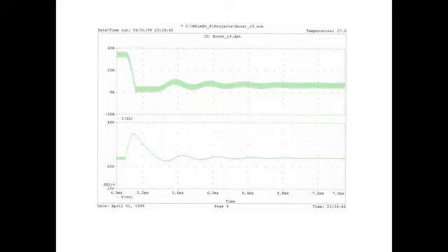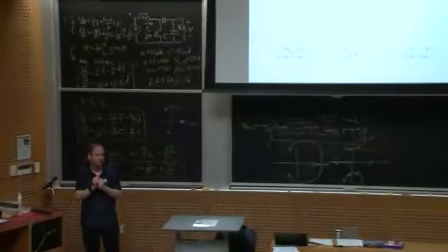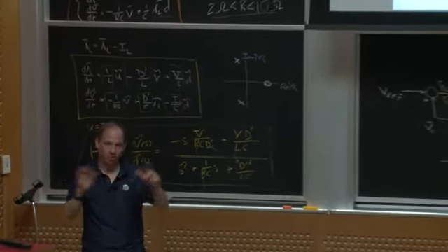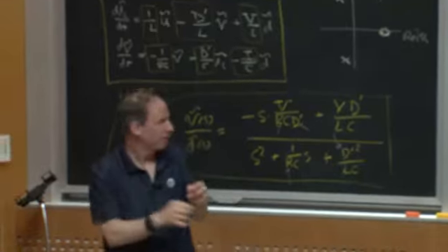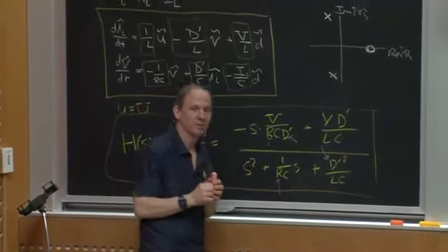So actually, that average model isn't quite right anymore. Okay? Now, if we simulate this, we actually do pretty well, but in the simulation we stick in a diode, we clamped it so that it wouldn't have the inductor current go negative. Why? Because this has a switch and a diode in it. Now, if you had 2 switches, this average model's perfect. It works all the time. It is still clipped. Like in our system, we can never have duty ratios greater than 1 or less than 0, so there is some clipping that goes on.